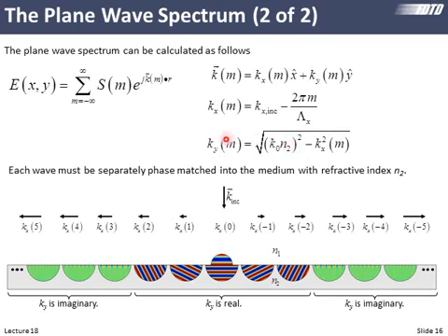When the longitudinal component is real, we're talking about these plane waves. Those are the only ones we care about when we're thinking about power being transported to or from a device. When this is imaginary, it's cut off. These don't contribute to power being transported away from the device, except for that one exception of electromagnetic tunneling that we're avoiding by placing our PMLs far enough away that they're not touching those evanescent fields.